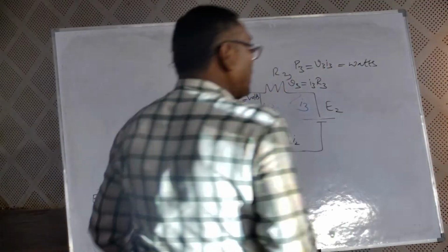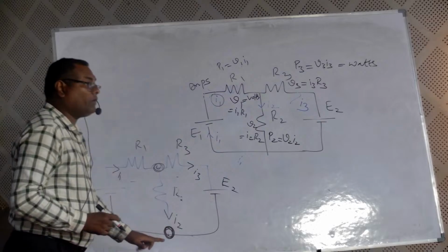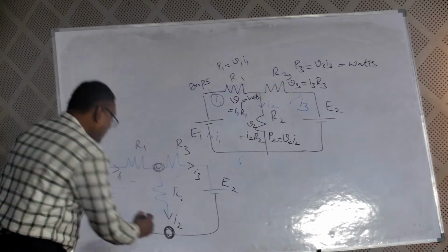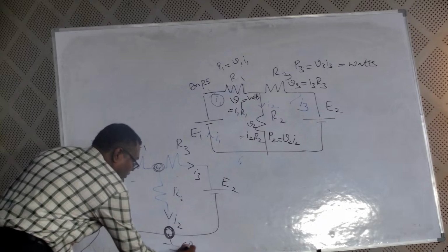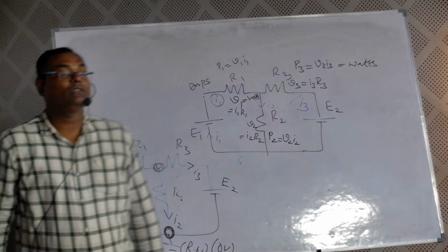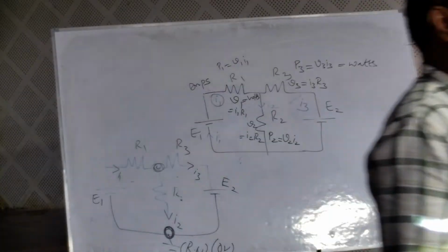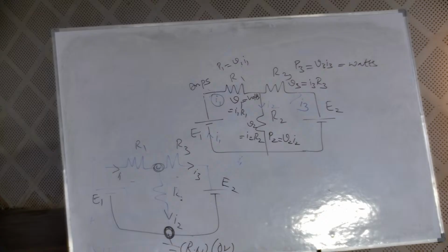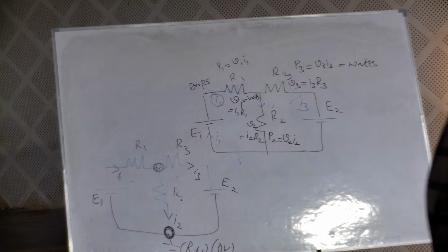You can take the top one or the bottom one, your wish, but in most books it is the bottom one. Make this the reference node; the answer is 0 volts. First, we find the number of junctions, here two. Then one should be a reference node. However many nodes we get, 5 or 6 or 3, one should be a reference node. Confirm.